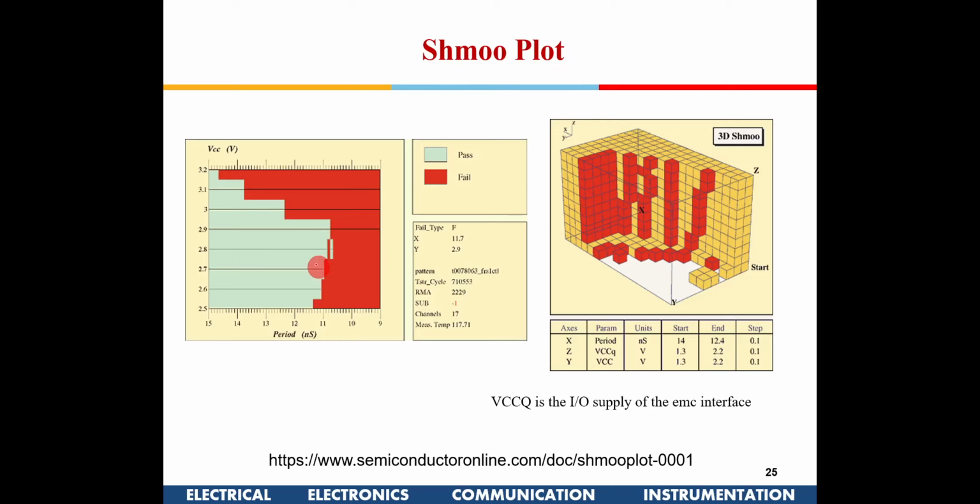This is known as a shmoo plot. What it does is, on a wafer there are several dies, right? I change the frequency here, going towards higher frequency, and I change the VDD. How many dies have failed? So these are the dies which are failing.